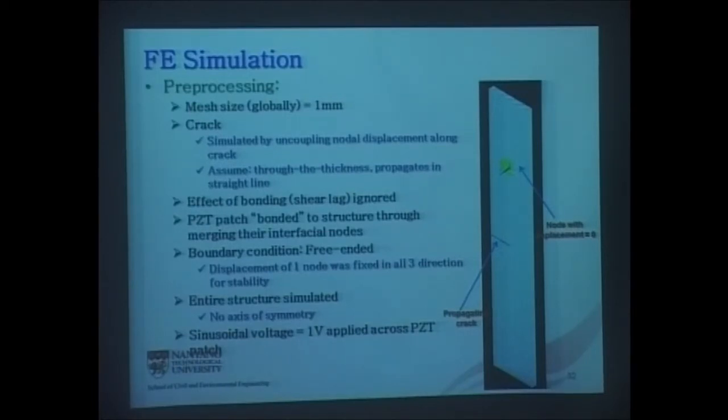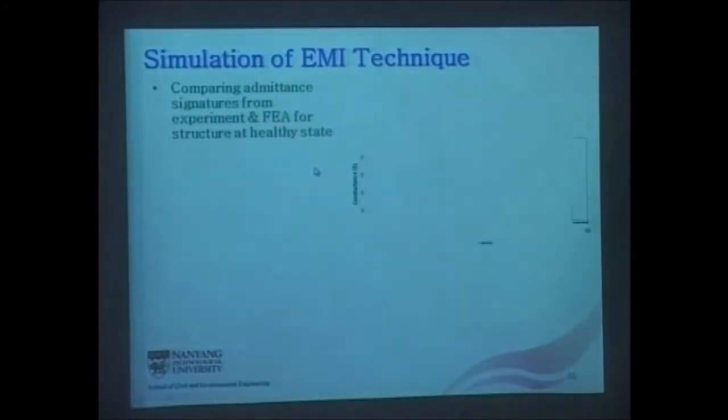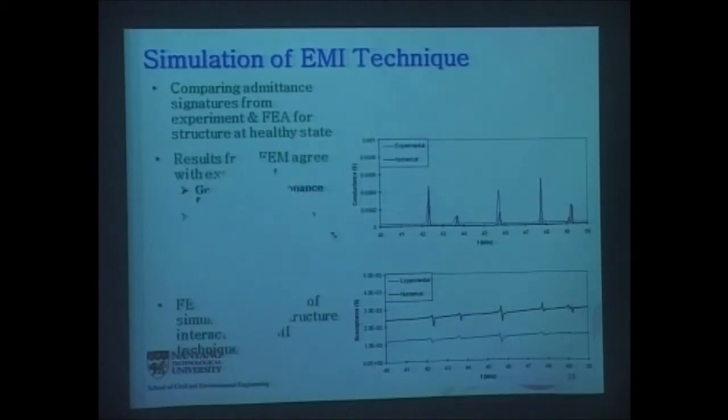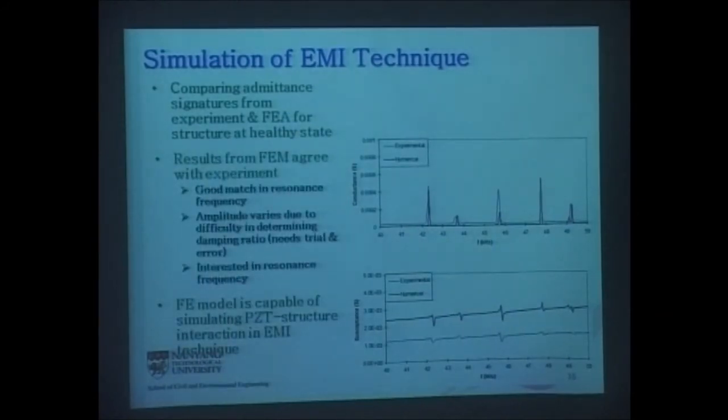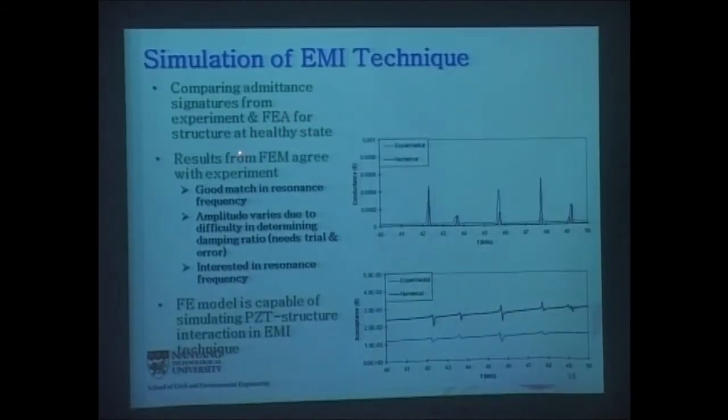This is very much a simulation, the PZT part. So, simulation of the EMI technique, comparing the admittance signatures with the experimental results at the crack stage. They agreed well, with a good match in resonant frequencies. These are the experimental and numerical results. Good match in conductance, and in the susceptance, that's the imaginary part. We actually have a very close match.